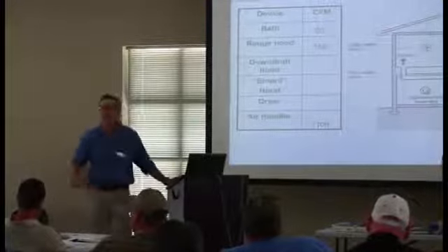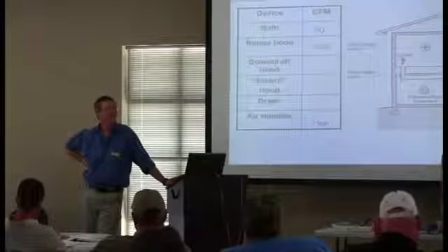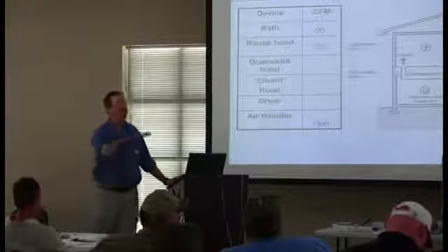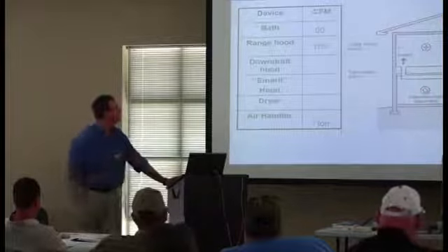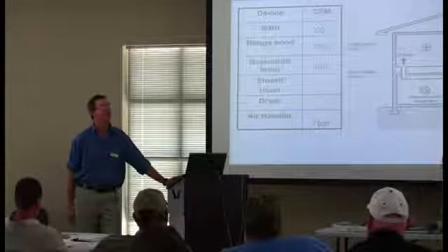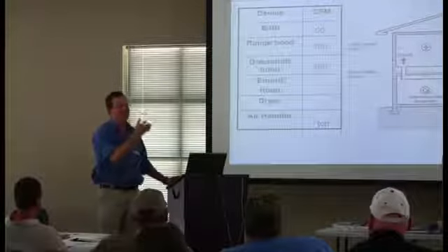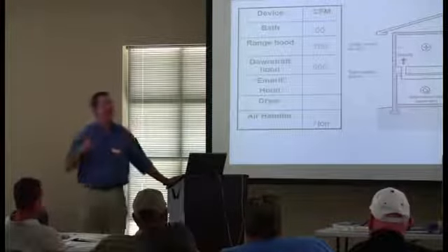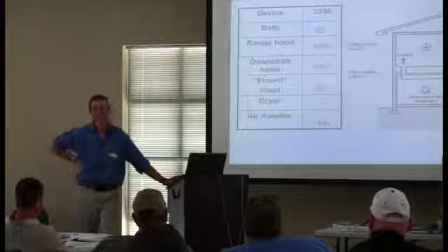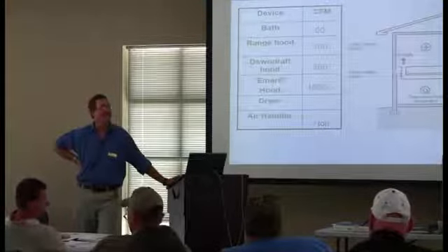Do you think that has to be more or less CFM for a downdraft? It's that stack effect you're trying to overcome. Bingo. You got it right on, John. So a downdraft might be as many as like 500 CFM. And then we have a special classification for the big ones that you mentioned. We call it the I want to be a chef kind of hood, and that's the ones that can push 1,100, 1,500 CFM.